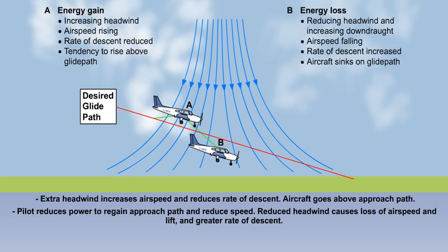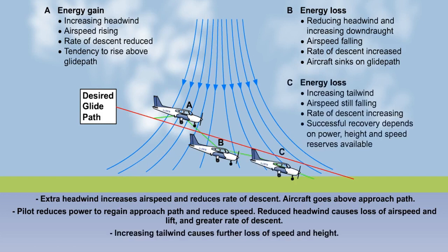If the speed reduces and rate of descent increases, set full power and adjust attitude, maintaining configuration and a safe margin of speed in case of further speed losses. If necessary, pitch to the onset of the stick shaker if fitted. It is safer to discontinue a destabilized approach than to try and re-establish stability in increasingly dangerous conditions. The same procedure can be used in the initial climb after takeoff.